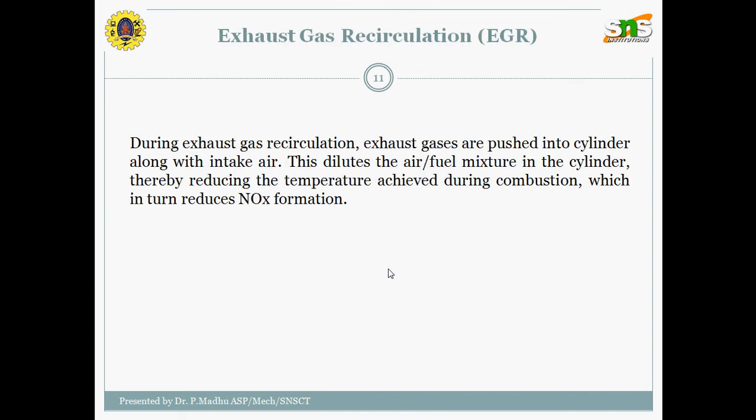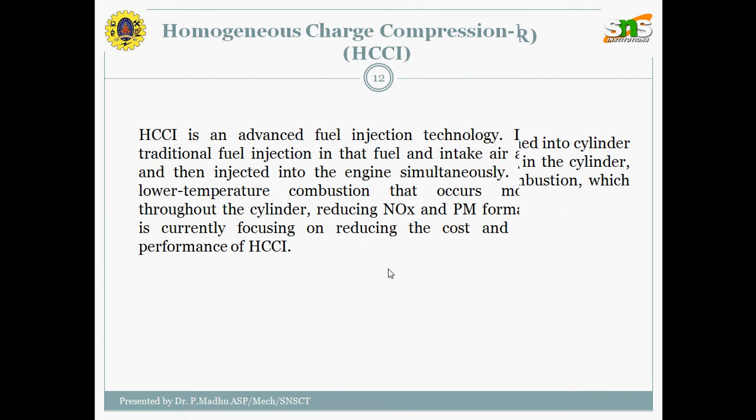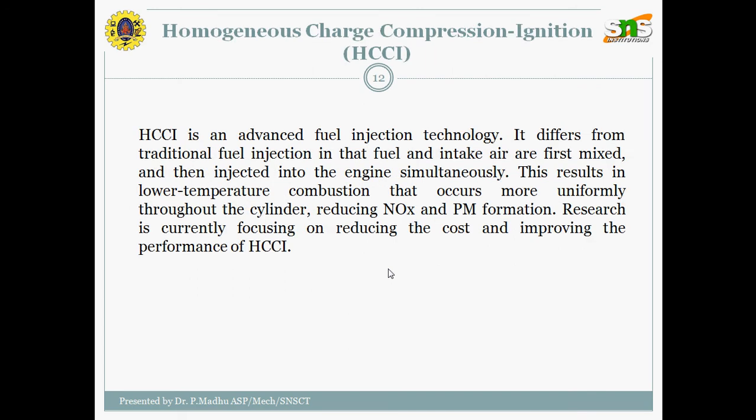Then exhaust gas recirculation, where the exhaust gas, which has a lot of heat energy, is pushed into the cylinder along with the intake air again. So the heated inlet air goes in, and the fuel is mixed into the cylinder. By this, we can reduce the NOx emissions, and also we can increase the efficiency of the diesel engines.